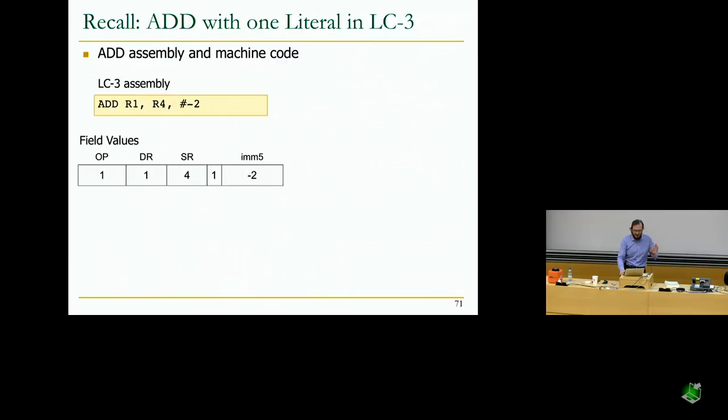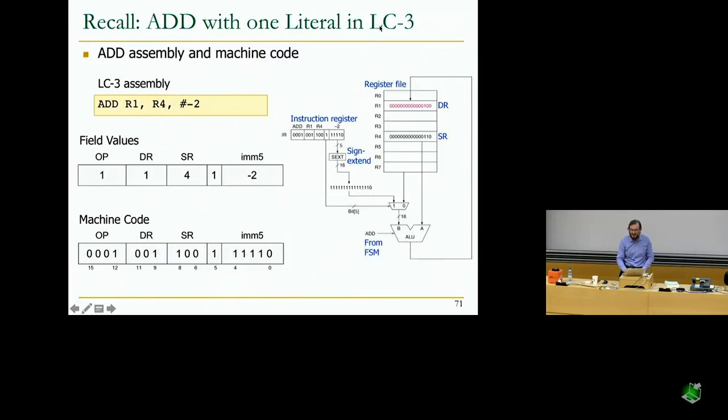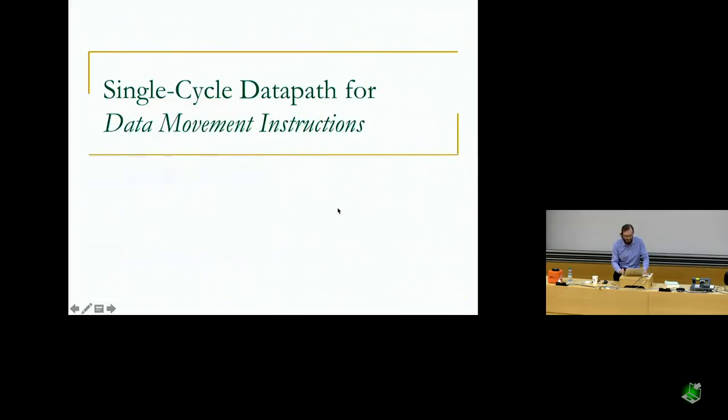Okay, so I'm not going to go through this, but LC3 did something similar, but we're going to see LC3 in the next lectures, and we're going to add very, very similar muxes. As you can see over here, the mux comes for an immediate instruction. You need to take this input of the mux. If the instruction is R-type, then it's not called R-type in LC3, but if the second source is a register, you need to take this input from this mux, and you need to set the control signal appropriately. Okay, those are the simple arithmetic instructions.